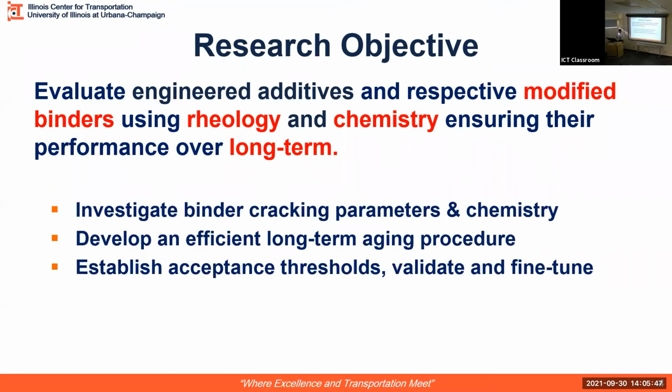Keeping that in mind, a battery of binder cracking parameters, which has been developed over the years in our industry and in the academic field, we looked at a variety of these parameters and also the chemistry of these modified binders. The idea was also to develop an efficient long-term aging procedure that can allow us to quantitatively assess the impact of these modified binders.